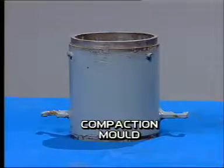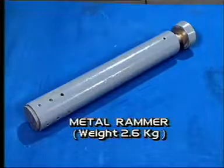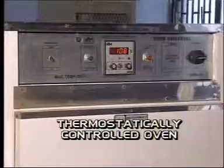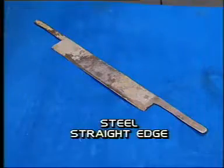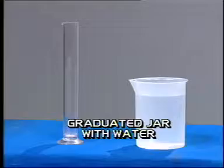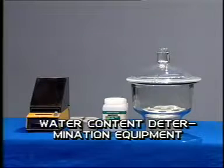The equipment required for conduct of this practical includes compaction mold, detachable base plate, collar, metal rammer of 2.6 kg, balance, thermostatically controlled oven, IS sieve of 20 mm and 4.75 mm, steel straight edge, mixing tools, graduated jar with water, air dried soil sample, airtight container, and water content determination equipment.